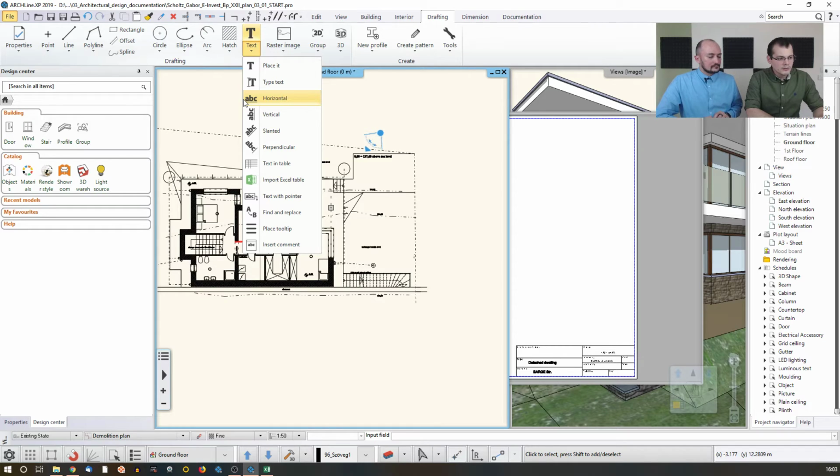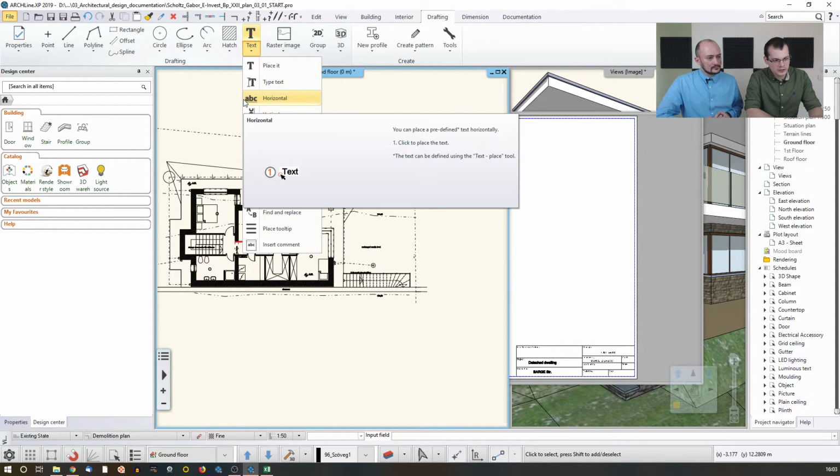Here's another one. When drawing drainage and pipe services on plan, is there any option to set Z values to the lines to show schematics for pipe isometrics if required for building control purposes? Z values are not automatically portrayed by default. So for instance, if you use the sweep command to create a pipe drainage system, then if you want to mark the elevation values on the floor plan or on the layout, you have to do that manually with text, right?